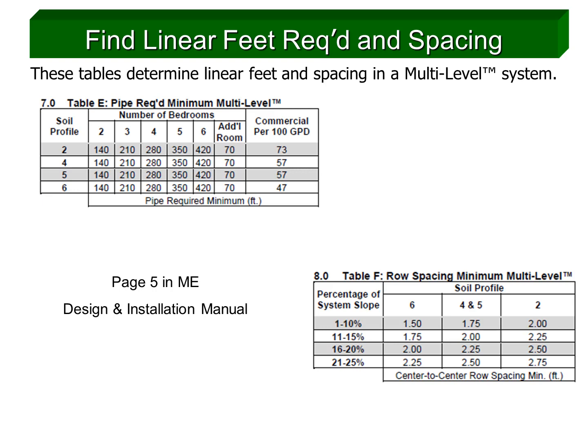In this example, the daily flow is 6 bedrooms, or 540 gallons per day. Right away, you should have noted this loading will not require a combination system because the daily flow did not exceed 900 gallons per day. So we can use a basic serial distribution layout.